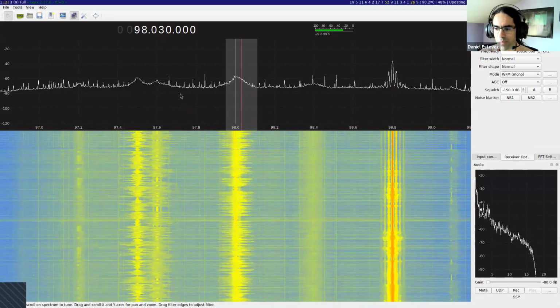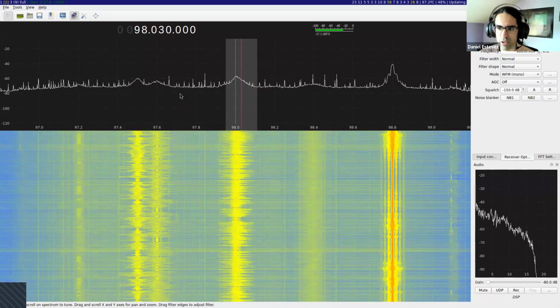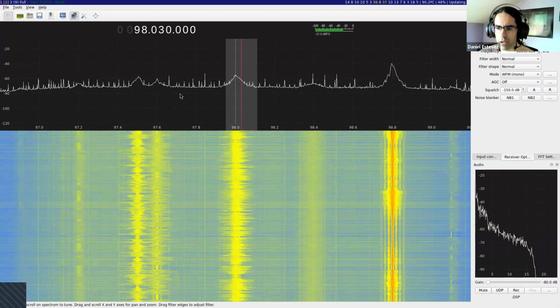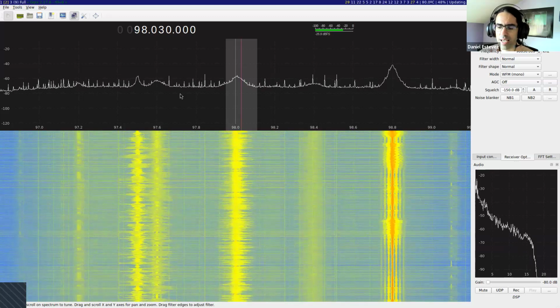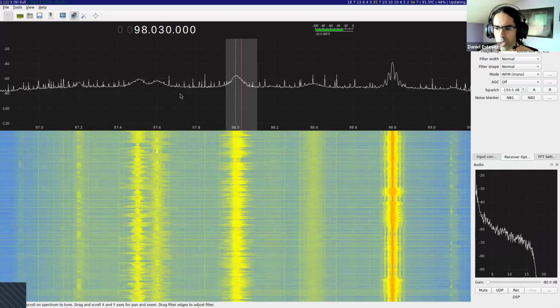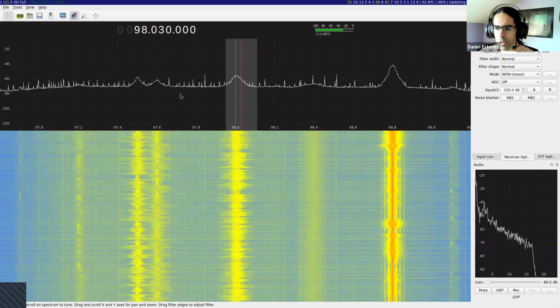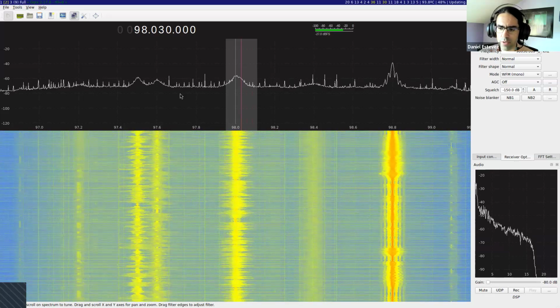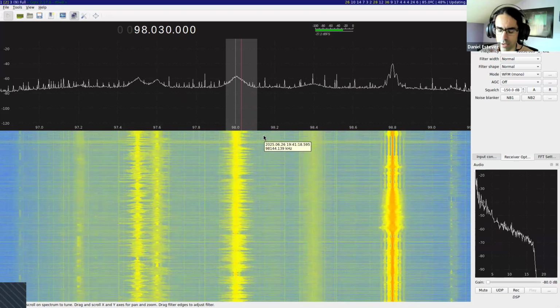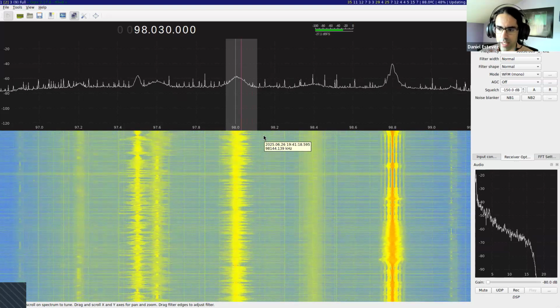So these are all the things going on behind the scenes of why we have complex numbers, why we need them, why they are useful. To summarize, they allow us to represent negative frequencies, which we use for this kind of hardware because it intends to shift the radio frequency signal down to DC, so down to 0 hertz, where it is easier to sample.